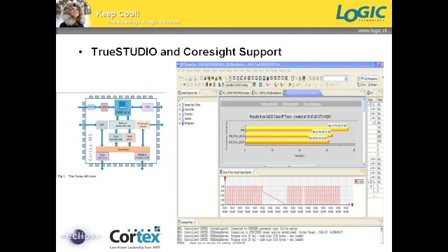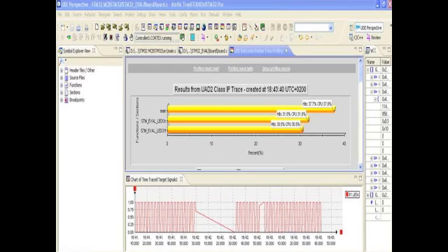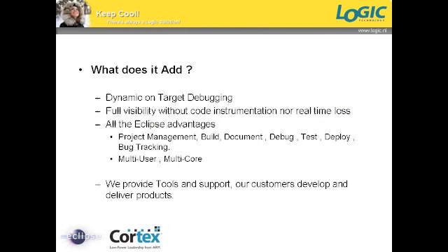As a last remark, we would like to highlight some of the high-end debug features provided by TrueStudio and DS5. They are all based on the CoreSight technology. Typically, one would expect to read and write into registers and have access to memory through the JTAG connector. With CoreSight, you get real-time code and data trace functionality on a running target. The example monitors I/O pins and profiles the software by tracing the program counter and data. Nicely integrated into Eclipse. This demonstrates how powerful low-end on-chip debug functionality becomes when it can be exposed in the Eclipse GUI.